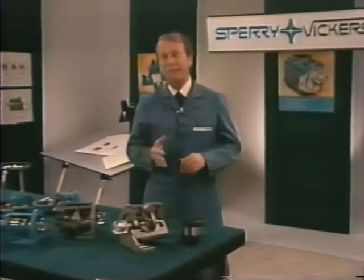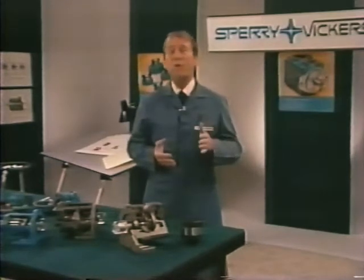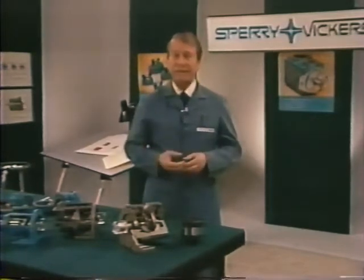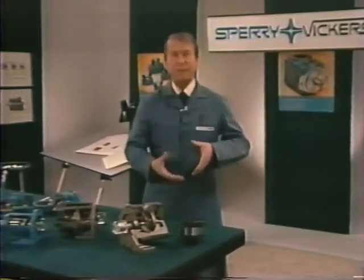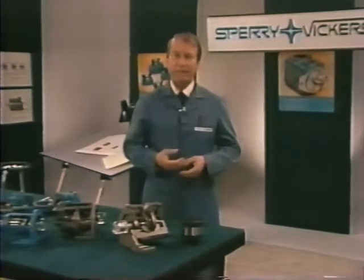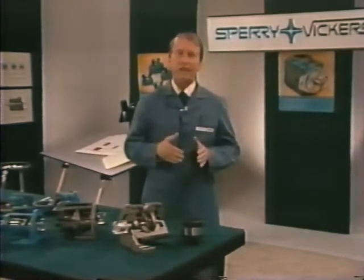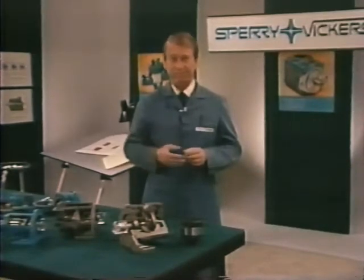They're usually assembled for right hand, but can be reversed by reversing the ring, rotor, and vanes. The cartridge is accessible after removing the back cover, which in this case contains the pump inlet port. It may be necessary to grasp the cartridge firmly and give it a slight twist as you pull it out of the body. An O-ring seal and backup ring around the hub of the pressure plate prevent leakage into the shaft seal area, but also resist removal of the cartridge.